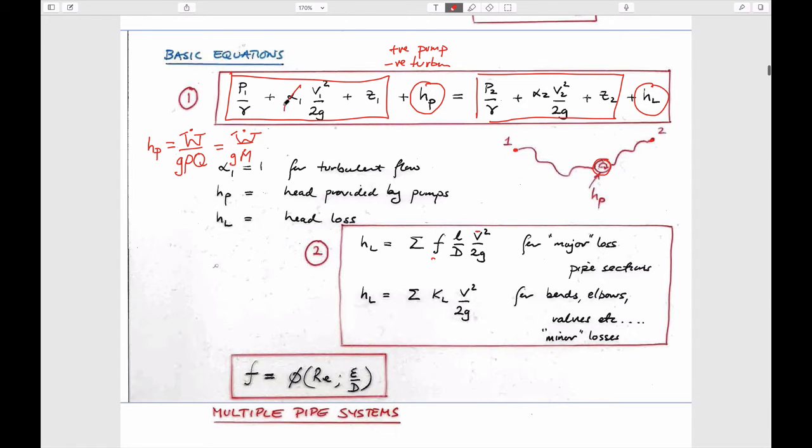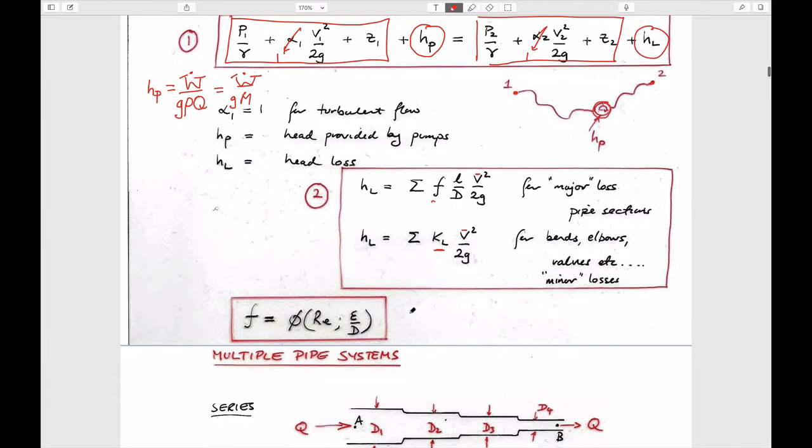This we've always assumed is 1 for all our cases. I don't think we'll deviate from that. And the fittings are again given in terms of a coefficient. It's assumed that the flow is always turbulent and therefore it's constant, so just a number between 0 and 1 typically. And the velocity head, again, within that fitting, taking account for the behavior in the fitting.